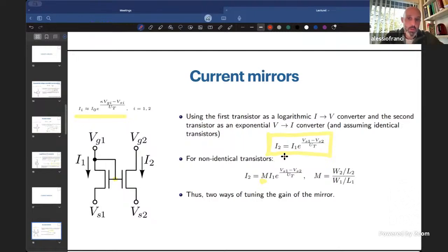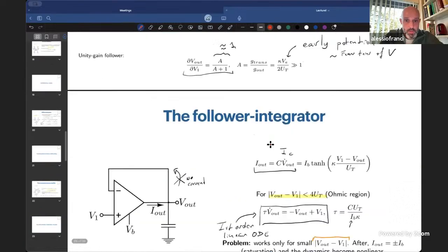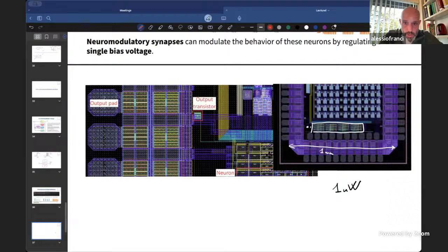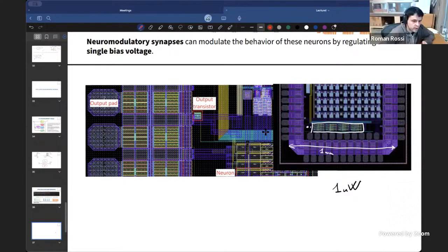And moreover, because of the technology they use, different parts of the wafer where your chip is put will receive different amounts of doping. So even the properties of the semiconductor will be different. Let me go back to the micrograph. A transistor that you have here will be different from a transistor that's here, although you ask them to make them identical.